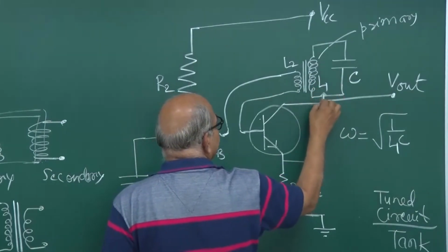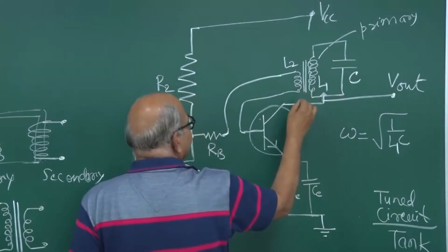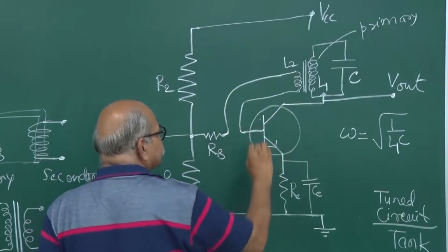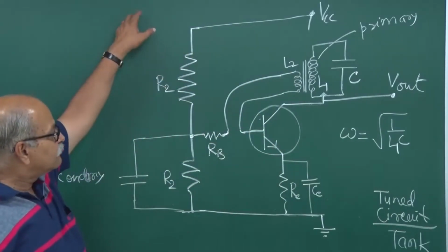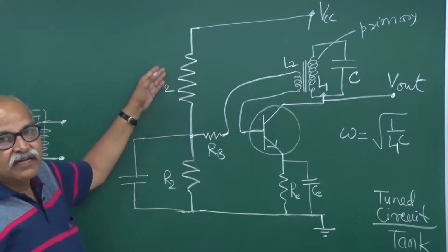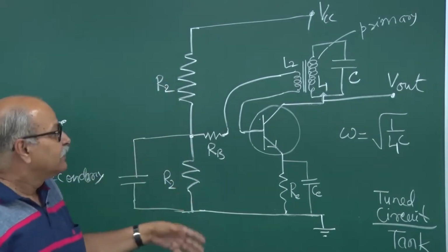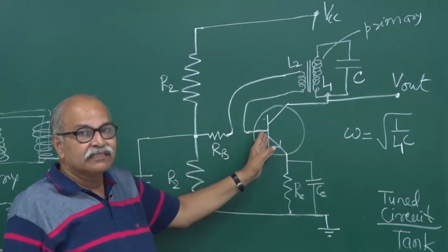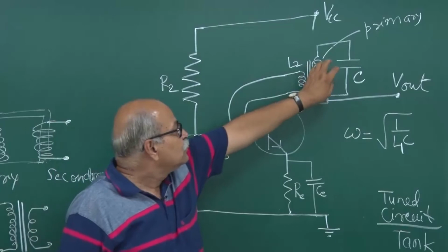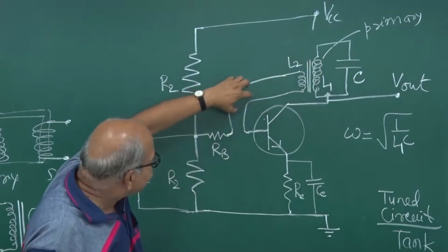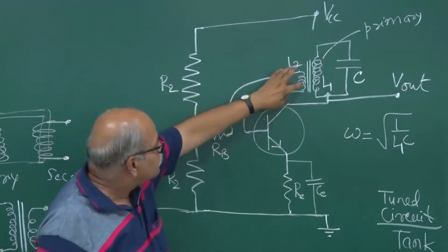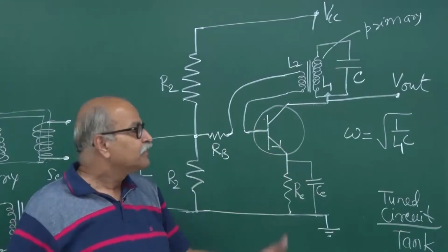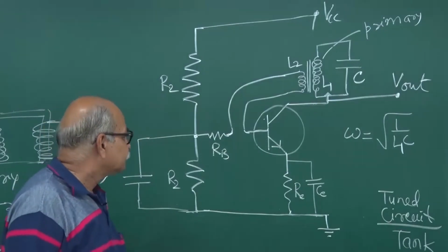This amplifier is giving signal into it, and what is it amplifying? It is amplifying this signal. So we are not giving anything from outside. From outside we are not giving any AC signal. It is only this AC signal which is coming and which is going into it. So that is how that tuned circuit, and this is that feedback network, feedback circuit, and this is that amplifier. So all those 3 blocks in the diagram, they are implemented in this fashion.